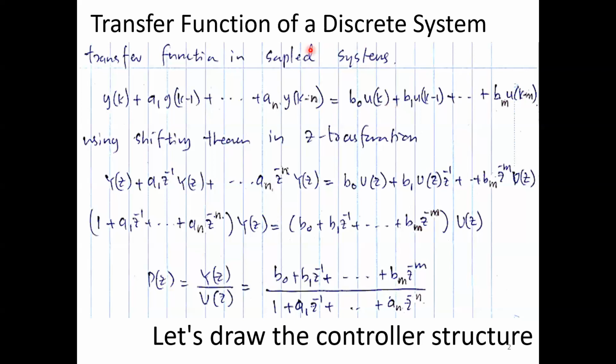And on the left-hand side, you can see all the responses, right? If it is a single input, single output system, which is very easy to understand, the response Y changes from K to K plus 1, K plus 2, and so on, right? So this is that signal. So if you want to build the transfer function, it is the ratio between response and the input signal, which is Y over U. Okay, so this is what you want to find out, Y over U. But in this format, you can't do that, okay? Because these are different times, different moments on time axis.